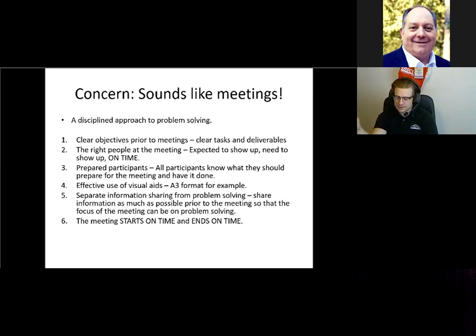Yeah, and that's a whole paycheck when it comes to design for assembly. The root cause of that problem might be that you have to talk to your engineer and say, when you draw this up, you can't make it so that this can be oriented in two ways. You need to add a feature that the customer doesn't care about, that makes this thing only fit one way. You see this a lot in clamshells and other things. We're accepting human error by saying there's no point in trying to convince the person to do this right. The customer doesn't care if this feature is here or not, but we're doing it for our own sake to bring robustness.